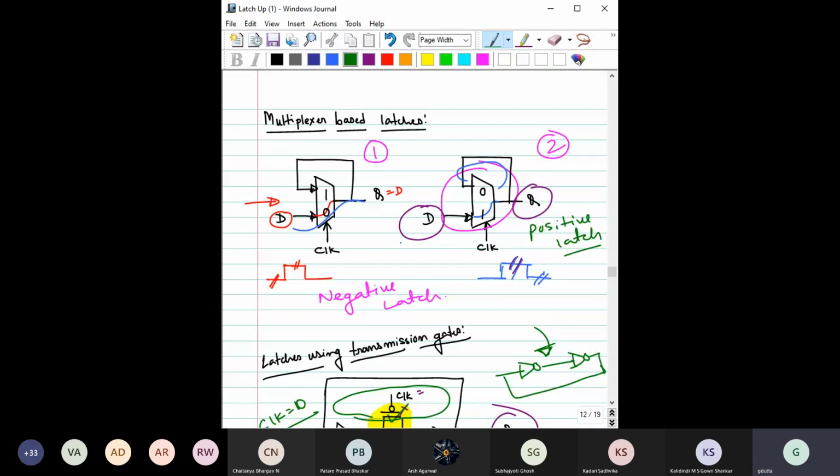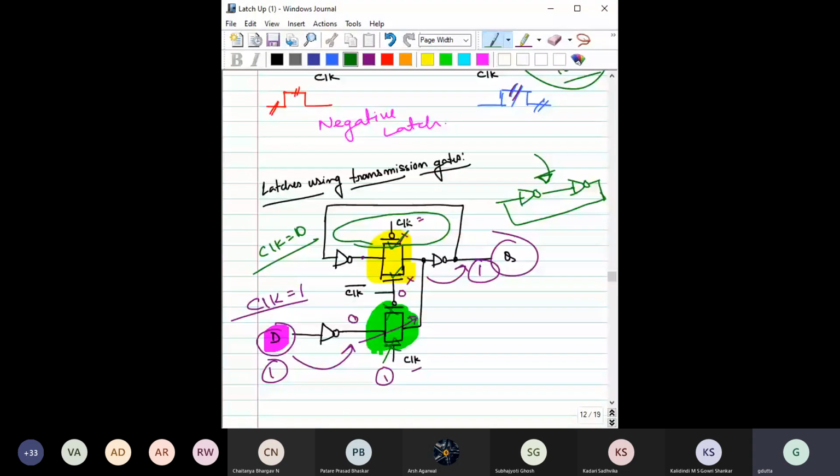Then this is basically the positive latch. Then if I ask you to implement the negative latch using pass transistor logic, can you do that? It's the same except you have to swap the clock and clock bar, and that will do it, right? Nothing else, right? Now, okay.